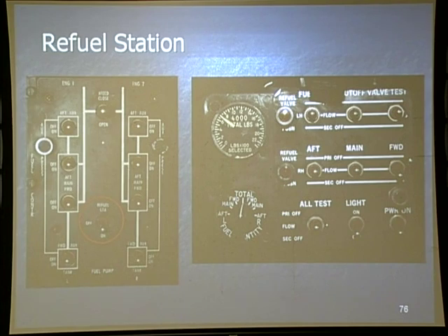Sure I can. Why? Because the refueling process itself is all pressure. It has nothing to do with electricity. It's going to do them all simultaneously. It'll still do them all simultaneously. The shutoff system will still work. Everything will work just as advertised. The only thing that won't happen is I won't be able to monitor fuel quantity, and I will not be electrically able to shut valves to limit how much fuel I put in a tank.